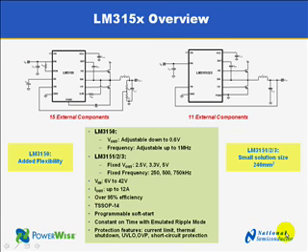Shown on this slide is the external components needed. For the adjustable, due to the fact that it's adjustable, we need a few more components than with the fixed version. The adjustable needs the resistor divider here, and it needs the R-on to set the frequency. All the other components are the same. So we have 11 components for the fixed versions and 15 components for the adjustable versions. This makes very small solution sizes.